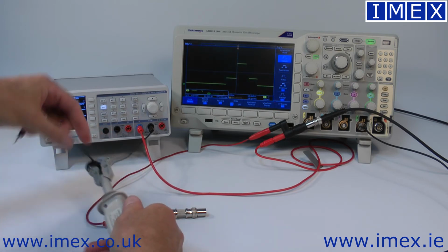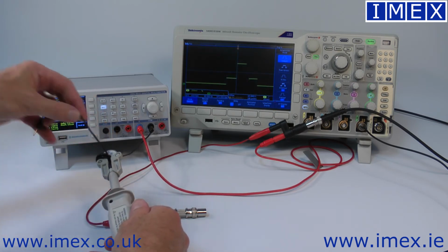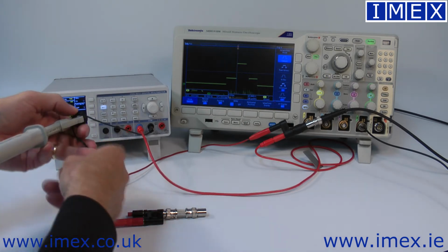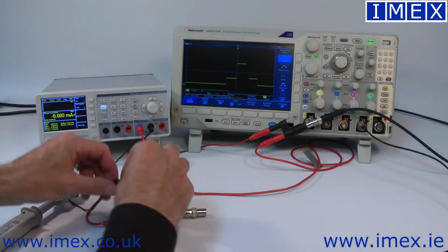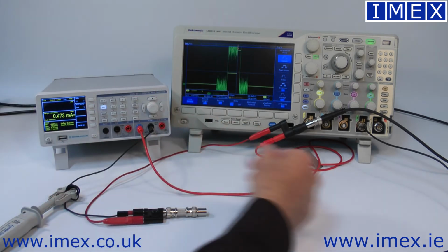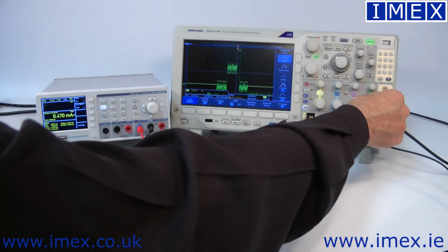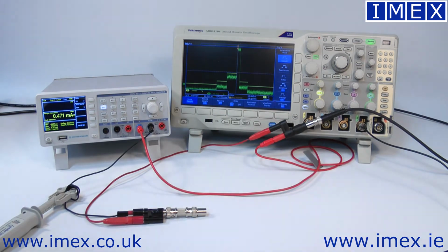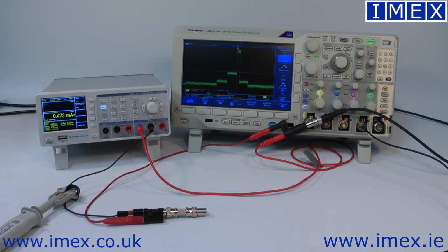The drawback, of course, back to front. The downside to this trick is we've increased the insertion loss, but for this low frequency stuff, it really doesn't matter. So pop that back down there, plug that in. Okay, you can see we've got a much bigger waveform. Pop this down. Okay. Adjustment 0. So that's given us a current measurement we can actually make use of.